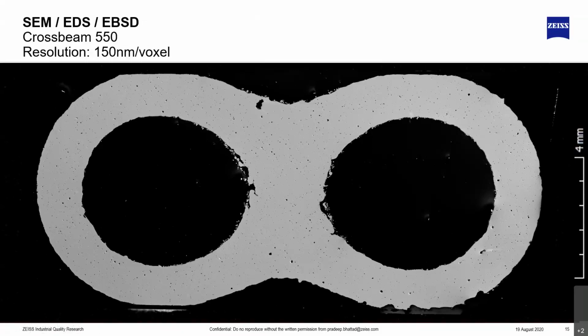In order to understand how do I get rid of some of this surface roughness, or is this surface roughness going to be a problem at all? That again becomes very important for operation of the instrument, because oftentimes just cleaning with different fluids in a static condition may give you a result saying, I don't have any more particles coming out in effluent, so I have cleaned the powder all well. But during operation and vibration, some of these things start becoming loose.